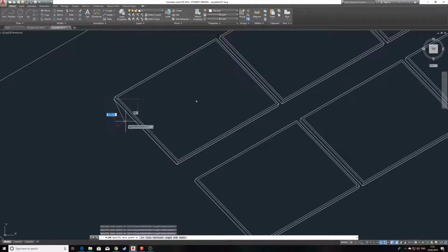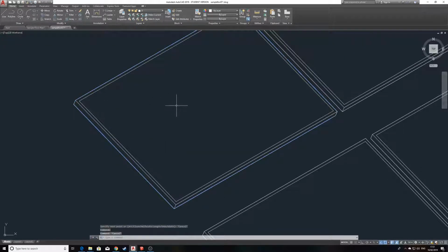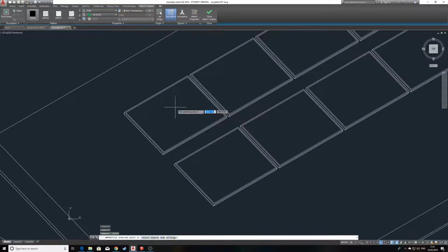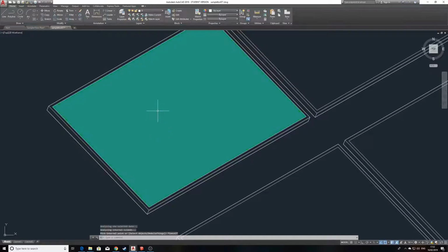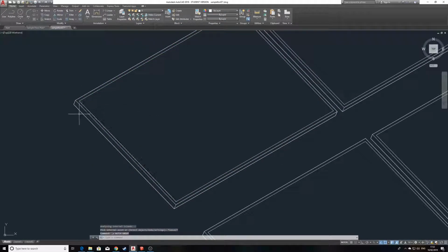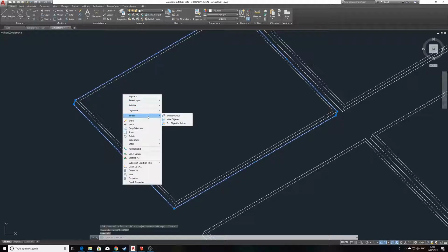So there we go, polyline is drawn. Now if we went to hatch this straight away, it wouldn't quite work because there's all the other lines as well. So we'd need to hatch that main section, hatch the sides and all the different faces that make up that panel, which we could do. But a quicker way, if we just undo that, is we select our polyline, right click, and go on isolate.